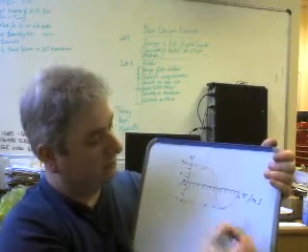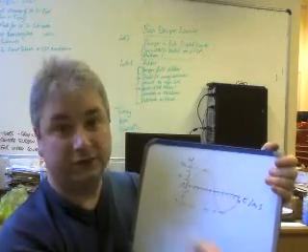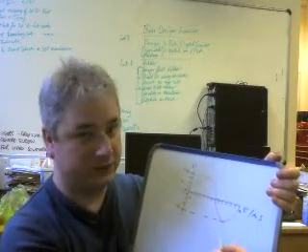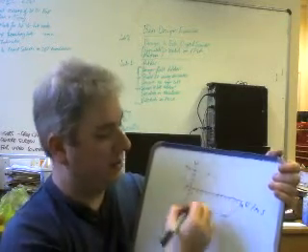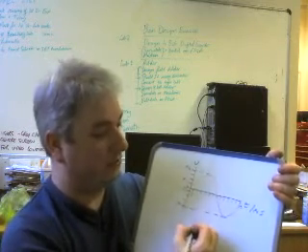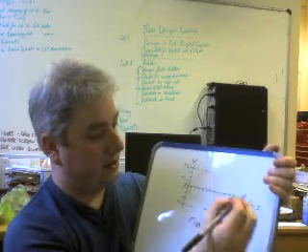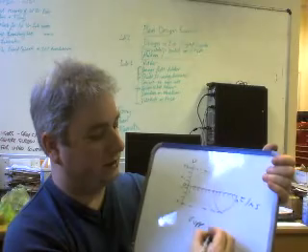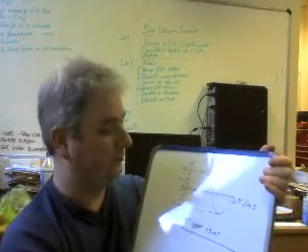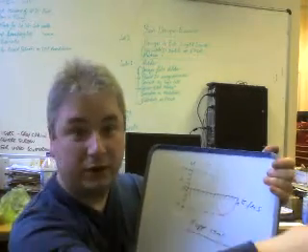So it is 4 volts amplitude, and 4 volts in what we call the trough, because it's going negative. 4 volts amplitude is positive above 0. From peak to peak, add them together, 8 volts. So we have 8 volts peak to peak, and a period of 13 milliseconds. Done. And that's exactly how you measure it from one of these oscilloscopes.